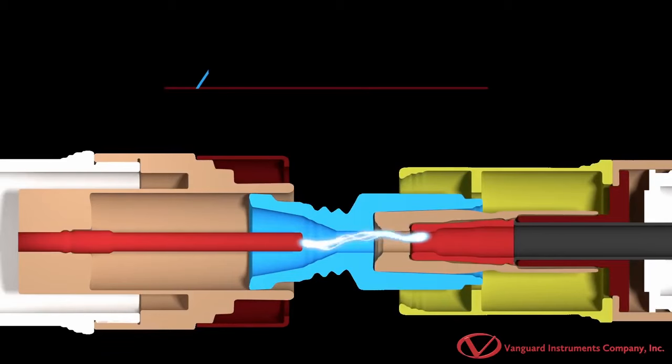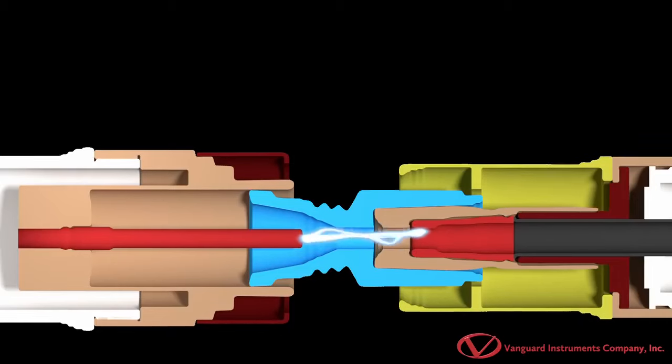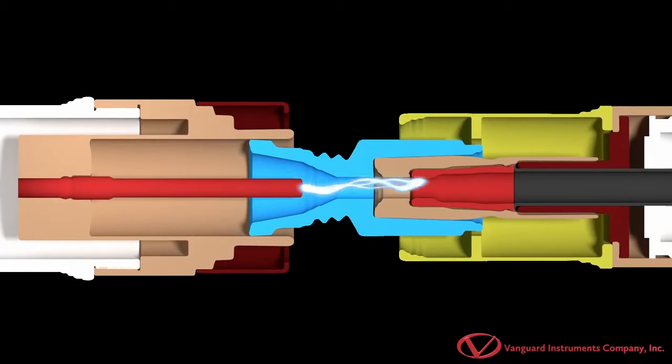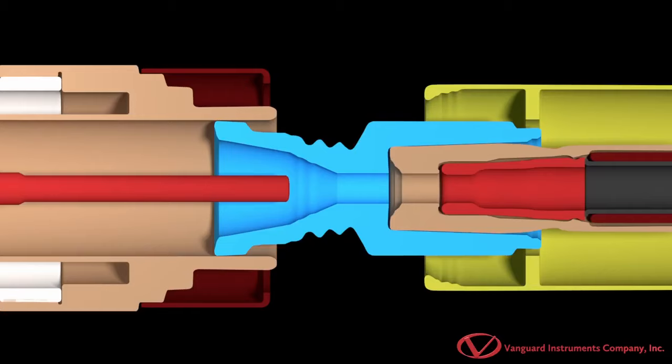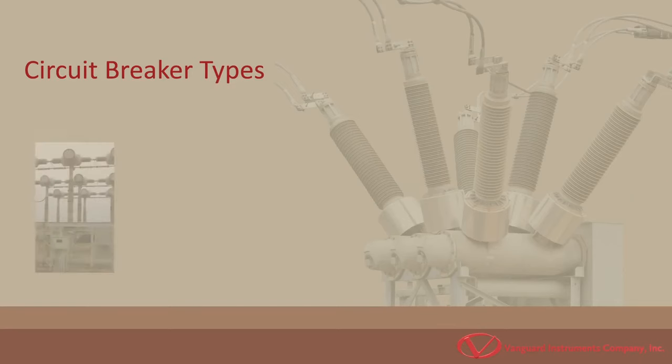Every arc extinguishes at every zero level and reignites individually after crossing the zero point due to the presence of voltage across the open contact. In order to avoid arc reignition, the contacts must be separated at sufficient speed. So that is the arcing chamber.